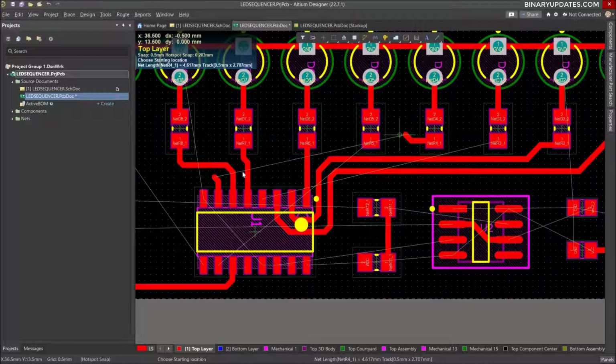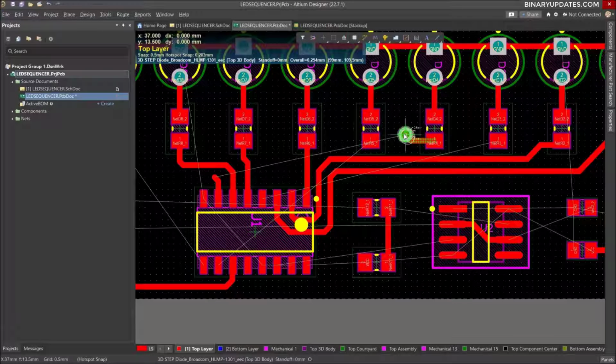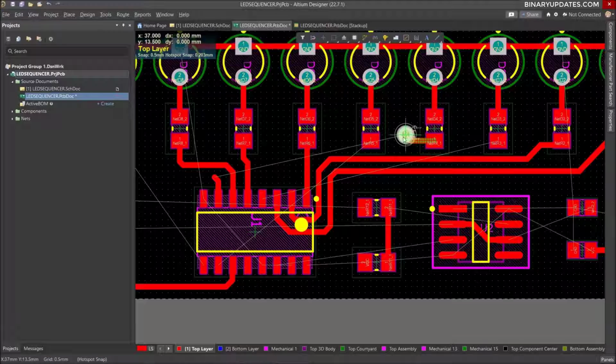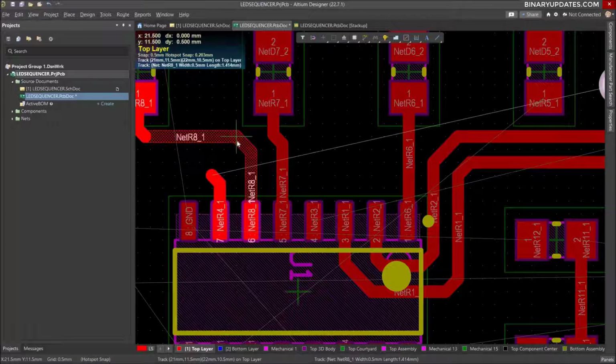Now you see they both are connected. Now I just press escape to get out of the routing, and then I select vias here. Look at this on the top, the sticky panel. So we can click here, and now I have the vias, so I can place my vias here. And when I place the vias, you see it shows me some kind of dot. That means it's connecting, so it's not really good to place it there. So what I personally prefer to do is click escape, and move this track a little bit up to create a little bit of space.